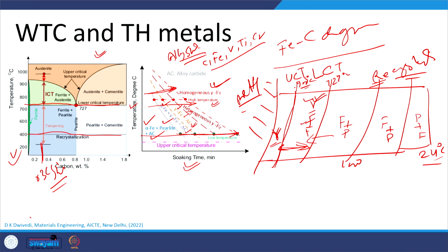But during welding we may not have this kind of luxury where homogeneity is attained, because the weld thermal cycle maintains the high temperature for only a short time.